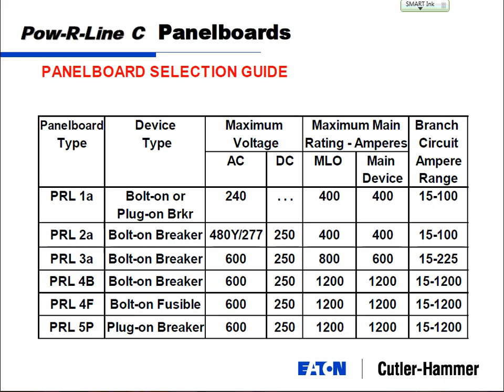So I'd say it's important to understand the concept of thermomagnetic, both protective features under one circuit breaker. And these are all mechanical type features. There's no circuitry. It's literally a couple pieces of metal for the thermal and a coil that creates a magnetic field for the magnetics. And it's that simple. I mean, it fits in something like this.